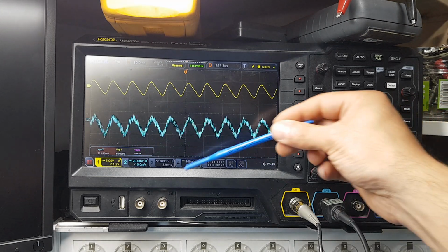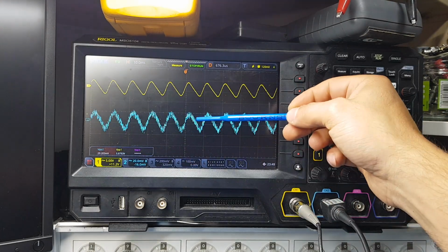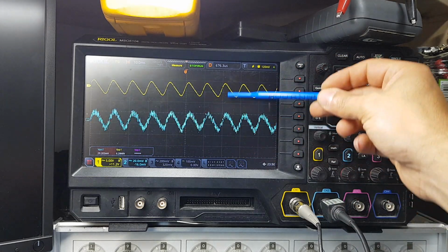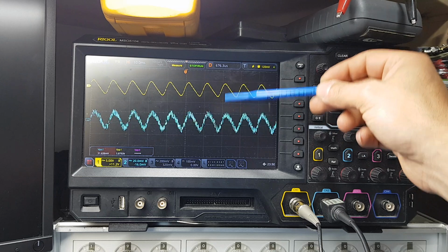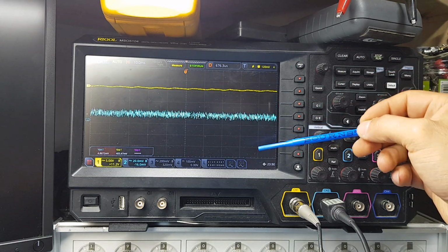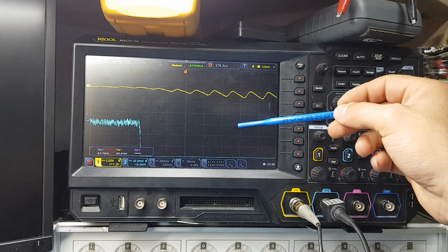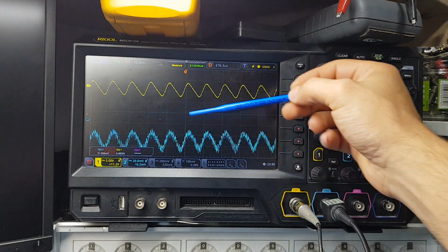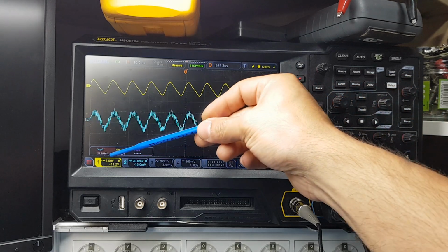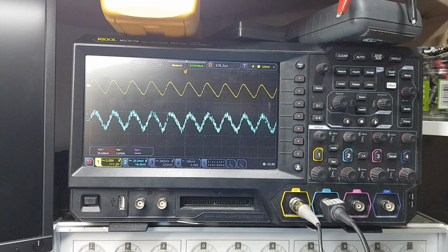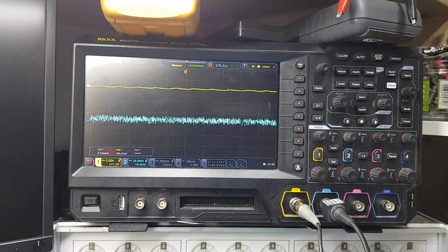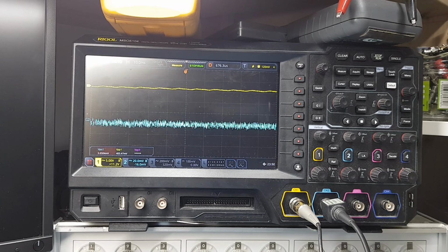You can see we're getting roughly about 30 millivolt of ripple, where the input ripple is around 6 volts. So it's doing a really good job of regulating and killing the ripple. If I stop that now, because my pass transistor is getting really hot. So we had 6 volt of ripple going into our Zener diode and our pass transistor, and we're getting about 30 millivolt out, which is not bad, it's still very good with just the lonely Zener diode and one pass transistor.